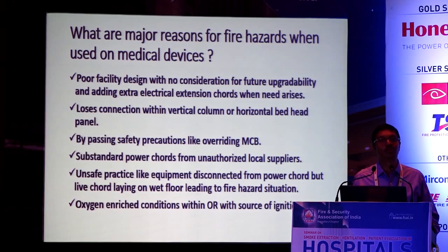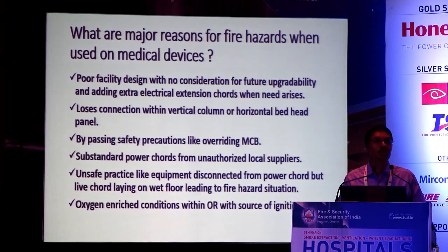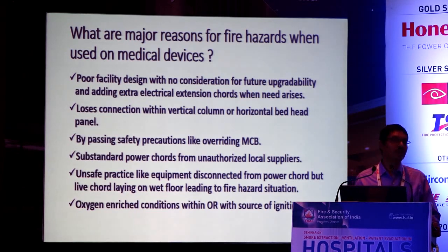Unsafe practices like equipment disconnected from a power cord, but a live cord lying on a wet floor. This has happened in my own hospital. In one of the ICUs, the equipment was being disconnected, but the power cord was still with the bedhead panel, and there was a wet condition, and there was an instance of fire. So these are the things which are practically happening.